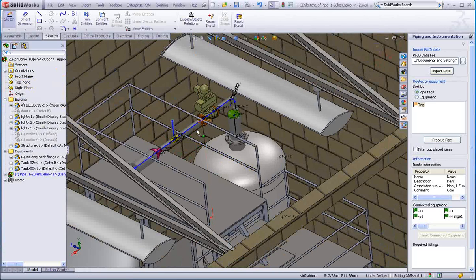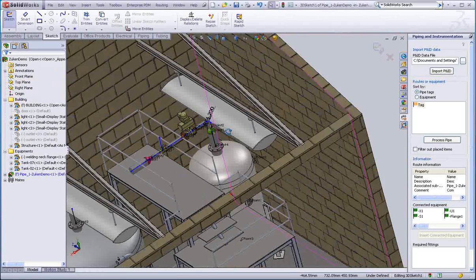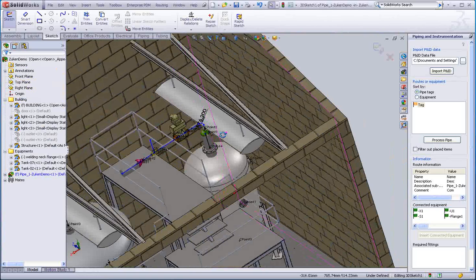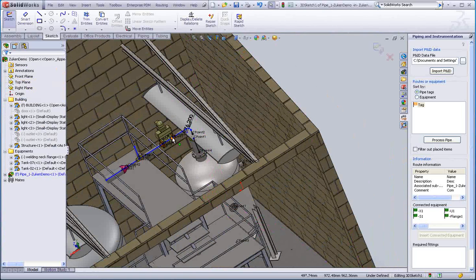so we've got that now forming part of our route. Okay, back into sketching, and we're just going to rotate that around a little bit. Move that. Perhaps we want the T point to route outside of that stairwell, like so. So we just drag it and move it around, and it reroutes for you if you do this. Reconfigures the length of pipe required.